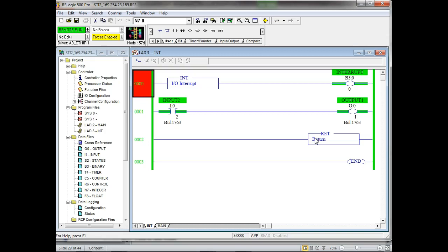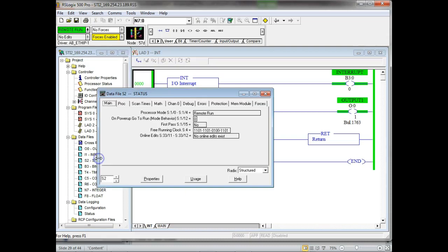Now the STI itself is not an instruction, right? You understand? This is hardware. It's being done by these clocks inside the PLC. This is S4, by the way. We use this every once in a while to set timing. So if I wanted to flash a light at a certain speed, then I might come up here and use this bit right here. What bit would that be? S4/15. This way the light would flash. Understand that?